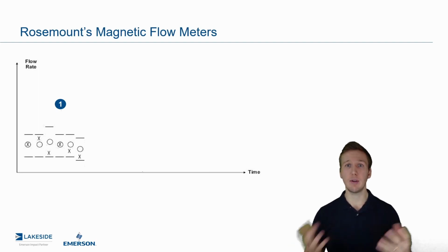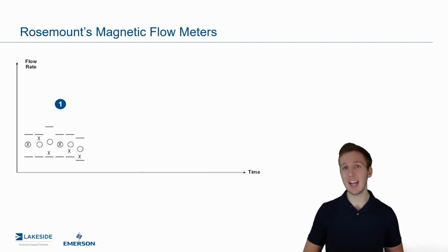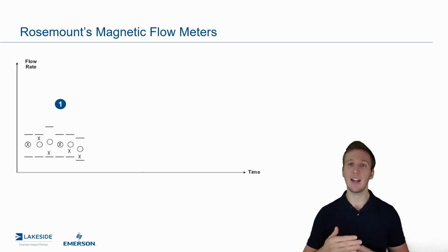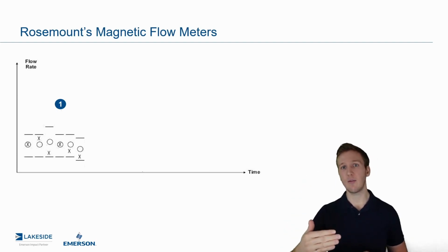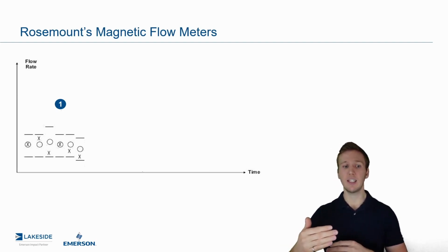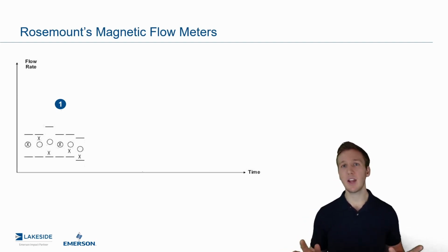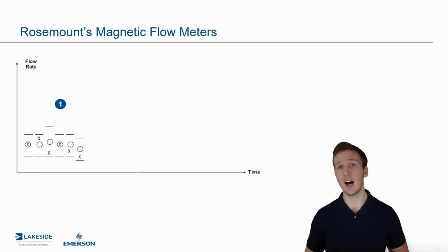And what it is doing beyond this, a little bit more sophisticated, is setting a threshold for where it expects values to be. Based off of nominal variance, it is setting these thresholds, which are represented by these horizontal bars. As you can see, after the second data point, we had a little bit of a jump high. That's why we had a threshold change on the upper side. And then as we started to have lower data points, both of those thresholds dropped. In either case, though, we have a pretty consistent, stable output that you'd have no issues controlling a valve off of, let's say.